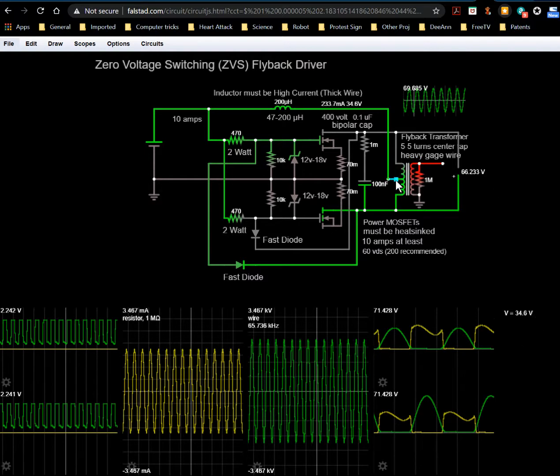So you can find out the resonant frequency by just plucking it like that, attaching power for a couple of seconds, allowing the fields to charge up, and then quickly removing the power, and it will oscillate at some frequency. It'll take a little while, but eventually it'll die off.